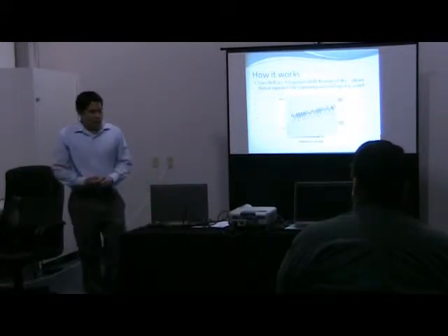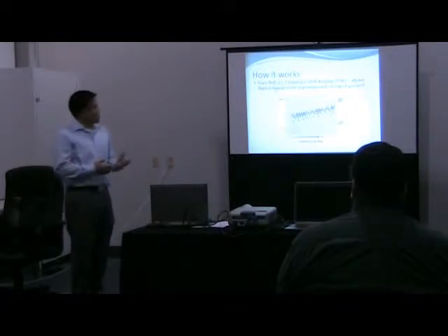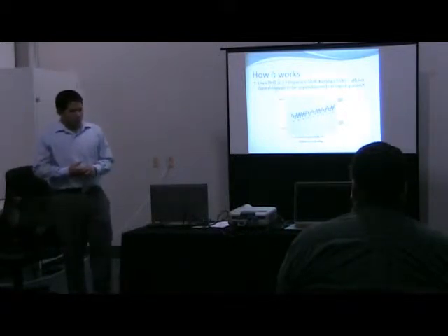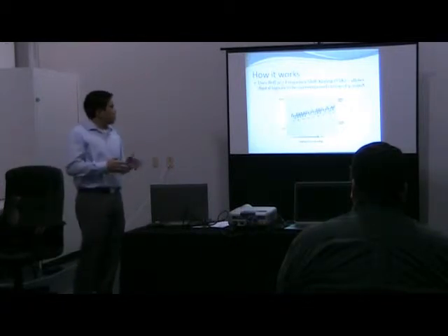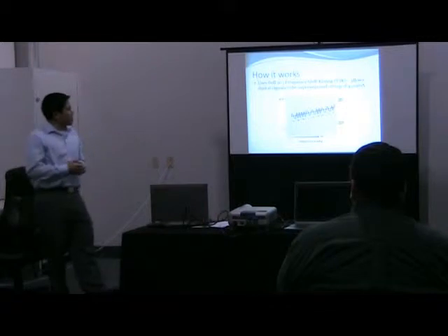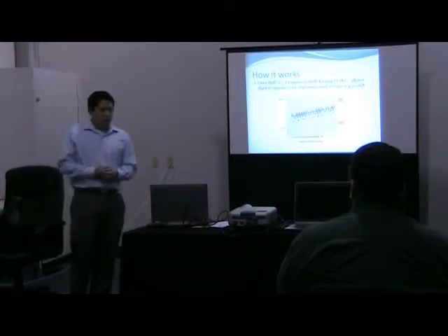So this is a little bit on how the technology works. It uses Bell 202 frequency shift keying, which is a modulation method which allows the digital signals to be superimposed on your 4 to 20 milliamp signal, where it gets decoded later back into a digital signal.